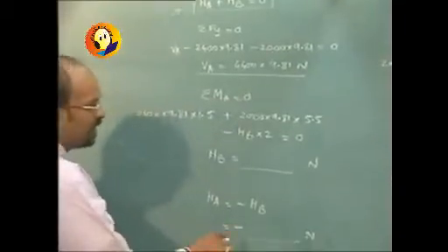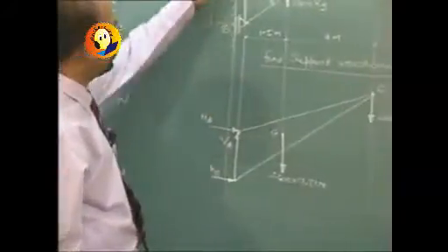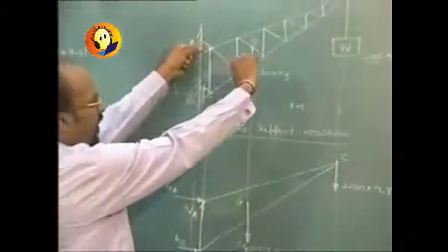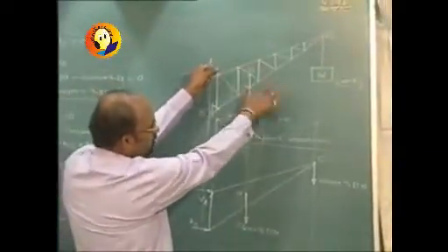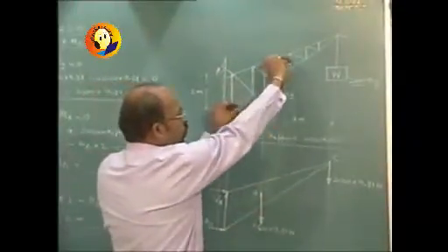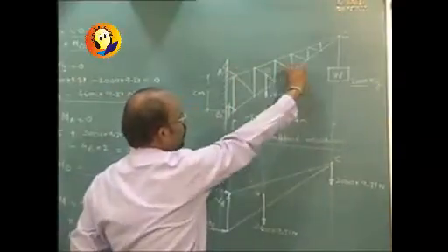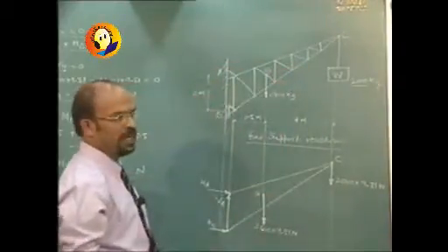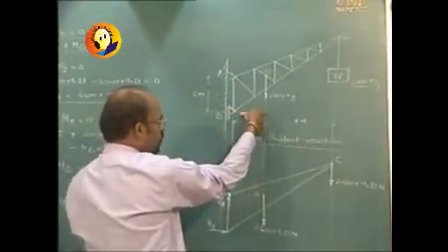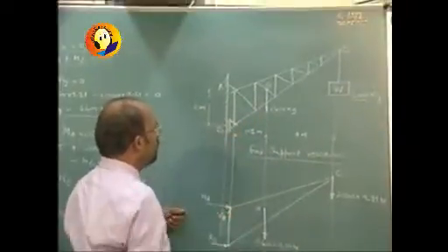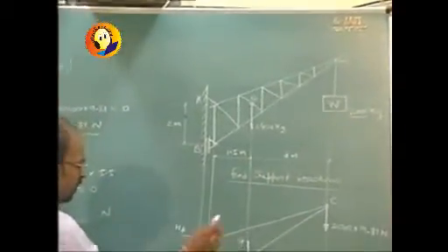Now when I am saying that HA will turn out to be negative, you will have to understand the effect of these two loads. If you consider point A, you will find that due to these forces, this point A will try to move towards right, because it is the moment which is given in this manner. It is going to rotate in this manner, so point A will sense a force which is pulling force towards right, and so the reaction at A should be negative. Whereas on B, this entire rotation load will come into picture, so roller will be pushed inside the particular wall, and so wall will be giving the reaction which is outward. So this direction will come out to be the correct one.